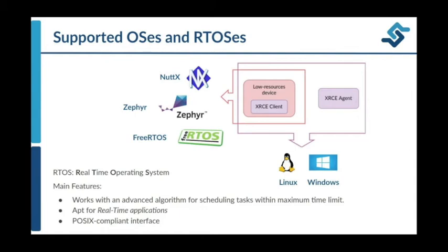So to address these needs, real-time operating systems rely on an advanced algorithm for scheduling tasks, which has well-defined time constraints. So for our Micro XRCE client, there are many such RTOSs, and our client crucially supports the 3 RTOSs shown here that are NuttX, Zephyr, and FreeRTOS. All of them on top of this scheduler expose a POSIX compliant interface.